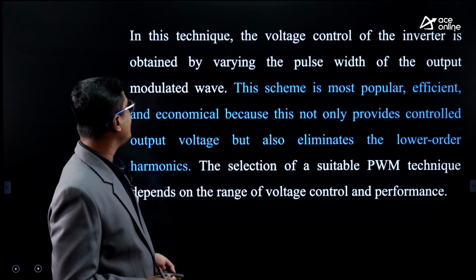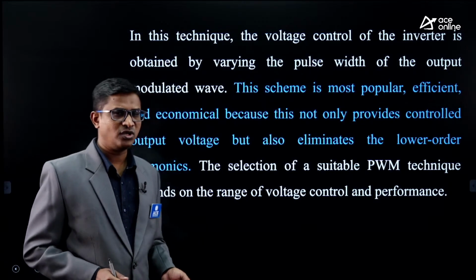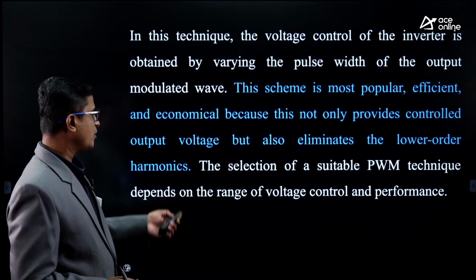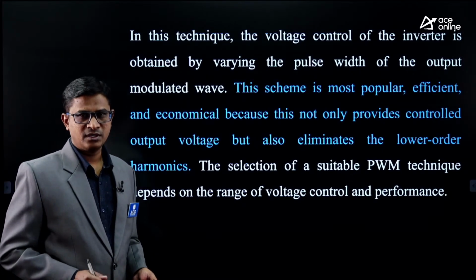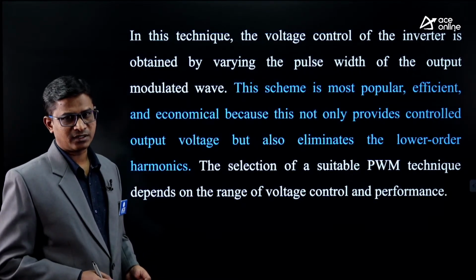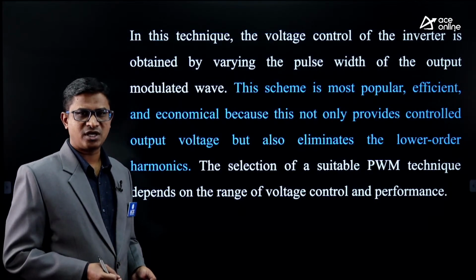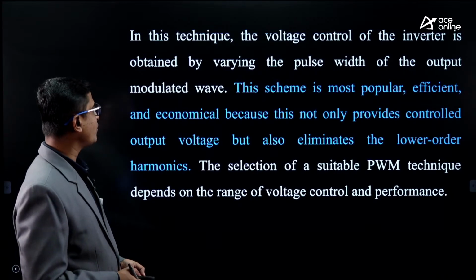So in the internal control of inverter, where control is within the inverter, there are different ways to control the output voltage of the inverter. Those are single PWM, multiple PWM, and sinusoidal PWM. It is known as the pulse width modulation technique.